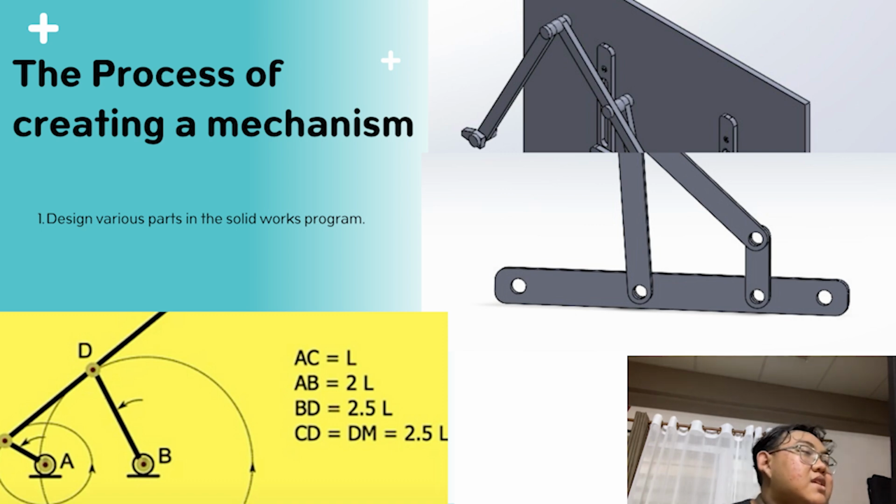After simulating the movement, we will work on the base connection. The goal is to increase the distance between the pins to avoid any interference during rotation. So we designed another support base for the linkage and drilled holes to attach it to the last acrylic sheet.